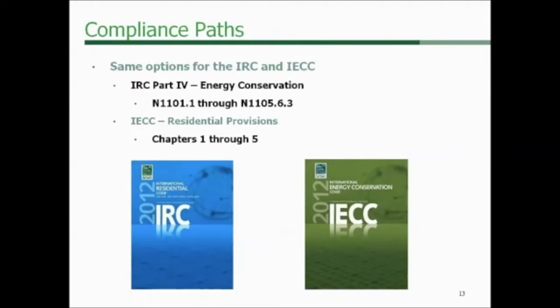So now we're talking about the compliance paths. Now the same options are in the IRC and the IECC, okay? They were made to align in the 2012 version. This was kind of new to the 2012 version, and as I foresee, it will continue to go that way. They made it so that there's really no distinction between the two. And so if I say IECC, it's just as applicable for the IRC. So whatever energy provisions your local jurisdiction's adopting, then those are it.